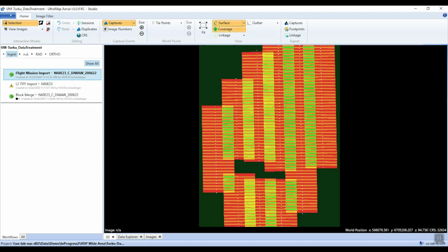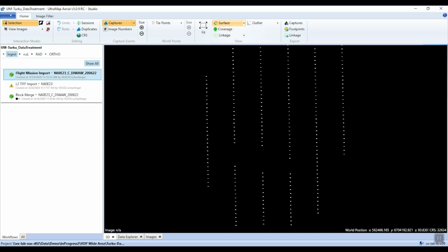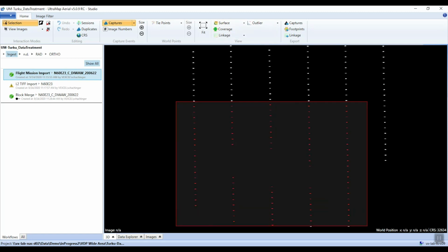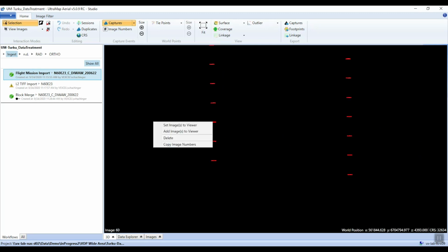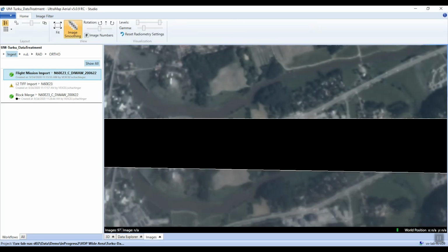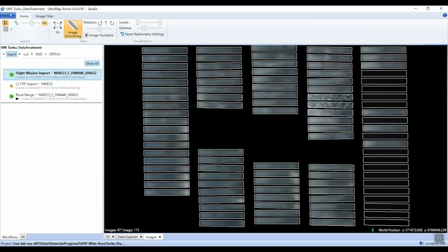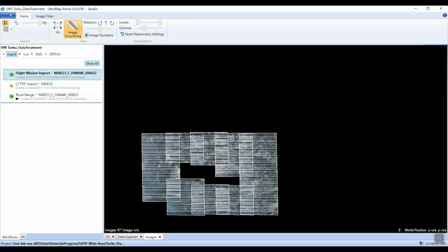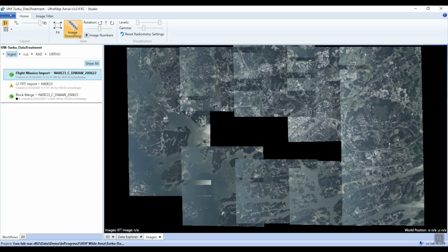This AOI in Finland was captured with an UltraCam Condor at 20 cm ground sampling distance, and two sensitive areas are within the project boundaries. VDP takes security concerns seriously, therefore this workflow is an essential part of our data handling. So in a first step, critical images were selected and removed from the default processing. Therefore, we see here these holes for the missing shot positions.